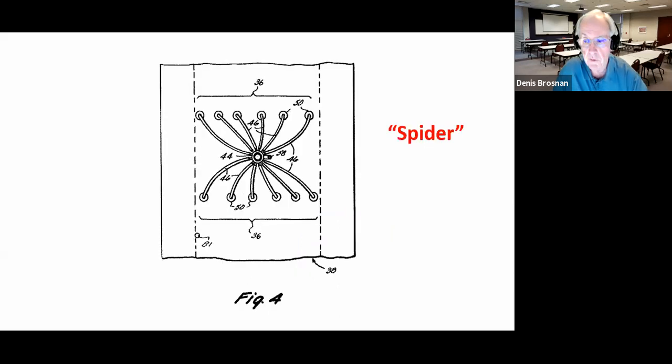So on top of the kiln, it looks like this, with one distribution device, in this case shown supplying about 12 burners. And so these look like little tubes on top of the kiln where the solid fuel is blown down into an opening in the crown of the kiln where it falls down and is ignited. A lot of people say this looks like a spider, so they call it a spider on top of the kiln, just common vernacular.